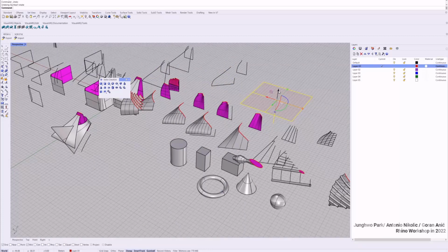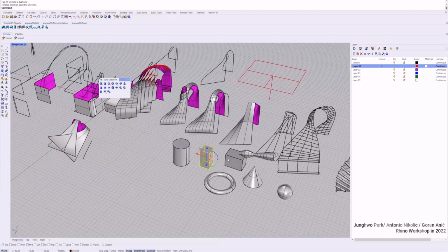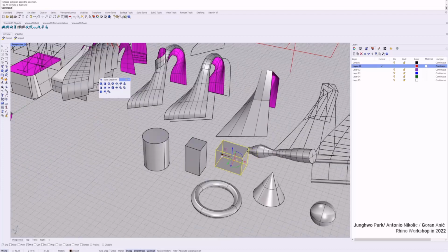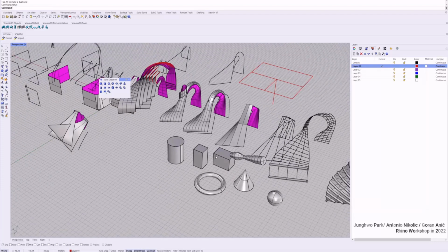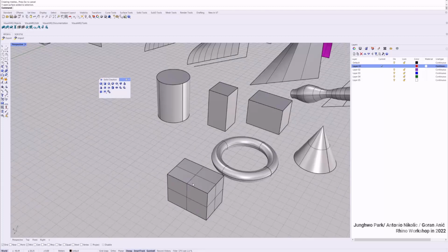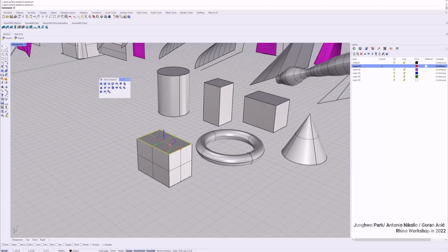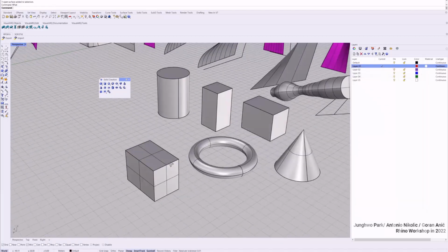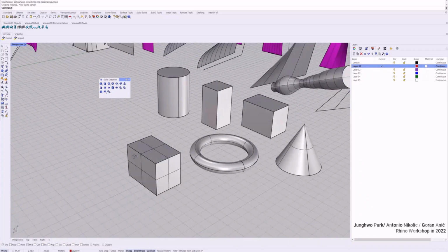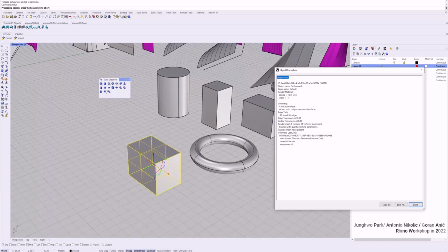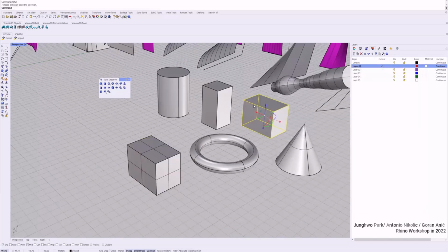As you can see, this is a solid object in Rhino. When you check what it is, it's called just an extrusion. But let me explode it. If you explode it, they become single surfaces. When you join them, it has iso curves, but it's different. Now it's called a polysurface. You see? But this is an extrusion.